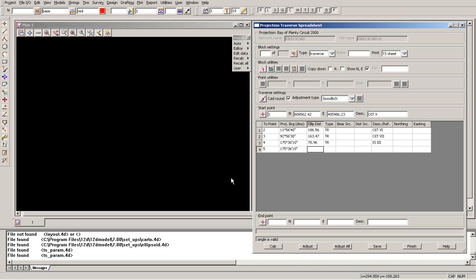We're noting that these iron spikes are online there, and 68.47, and again our traverse there, which brings us to iron tube 2, and then we're going to go to iron spike 1 at this point here, so that'll be 262.4450 and 86.60, again traversing, and again another mark that we've lined in, which is iron spike 1 in this case.